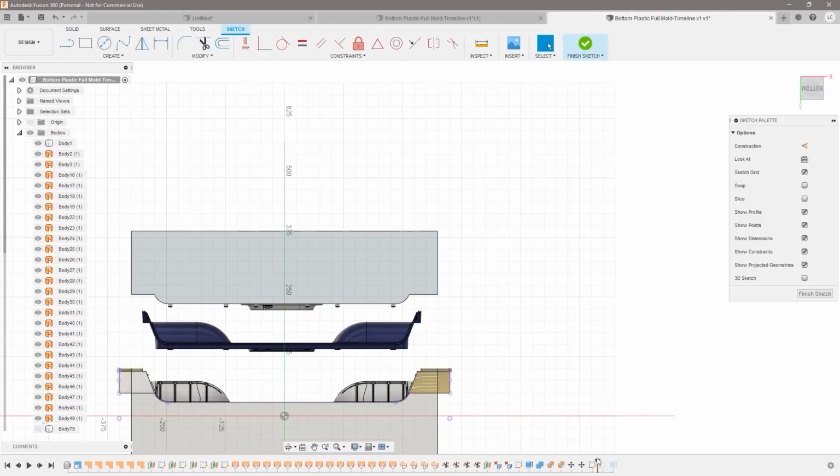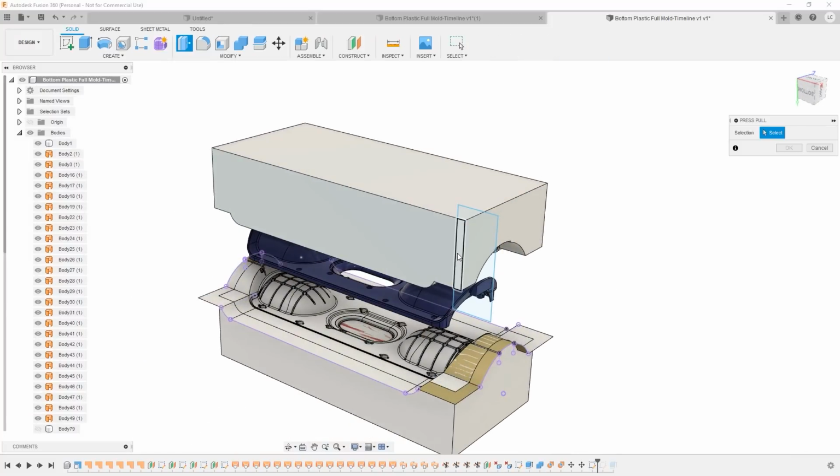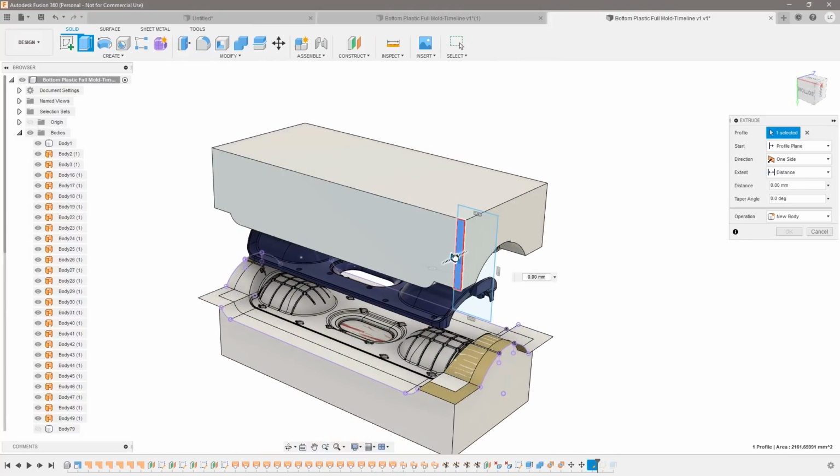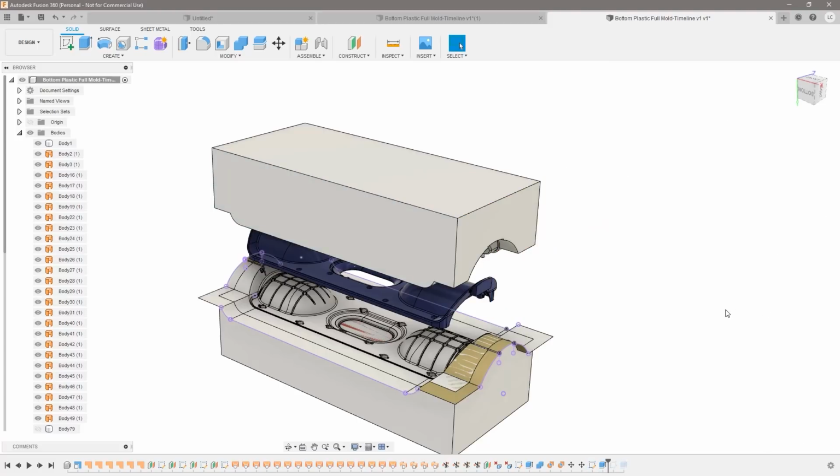This sketch I'm creating right now is happening before those two other ones. And if I cut this face away, I'm literally just cutting all this away. That means that I'm stealing that corner and that face ID. When I'm now moving forward, you will see that we still get the feature.